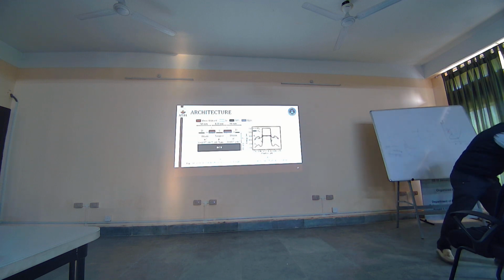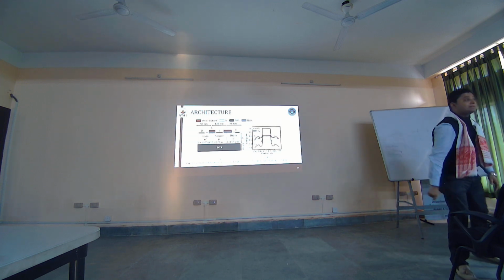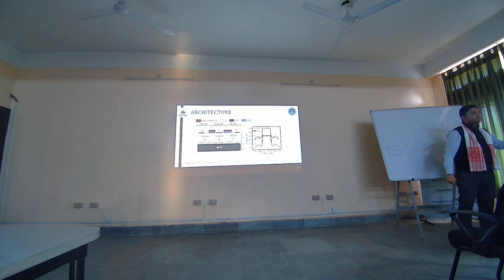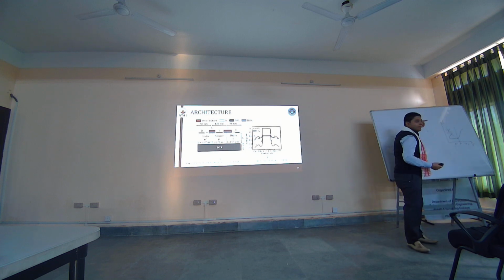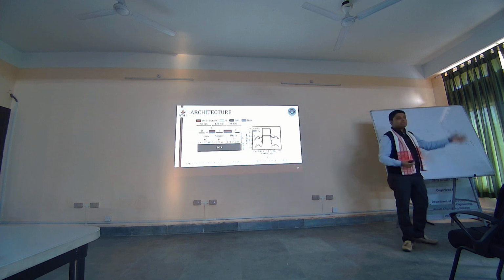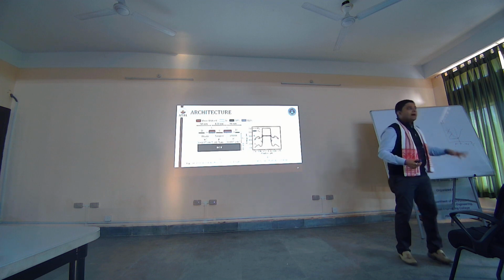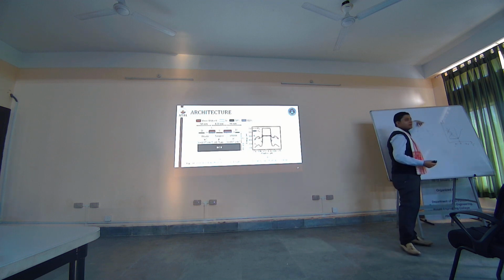Okay. Now, the problem with this is, if you are fabricating this device, there are certain issues because you have to put one gate from the top, one from the bottom. So there are, you can say, more steps that are required. Earlier it was simple because you had to put the gate on the same side.